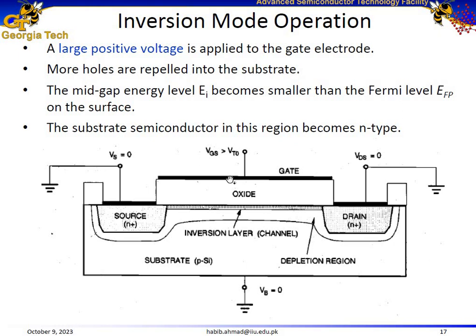We can have metal as well, but as we discussed in the photolithography lectures, we mostly use polysilicon because of the reasons we discussed for fabrication processes of VLSI design. A polysilicon gate has a higher melting point as compared to metal. So during the CMOS fabrication process, it's not going to melt down. So a polysilicon gate is preferable as compared to metal in a MOSFET.